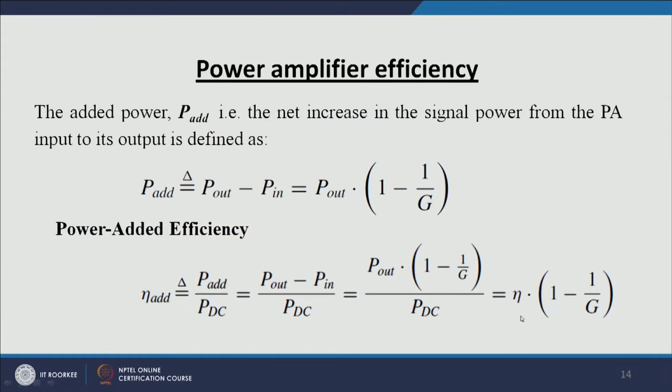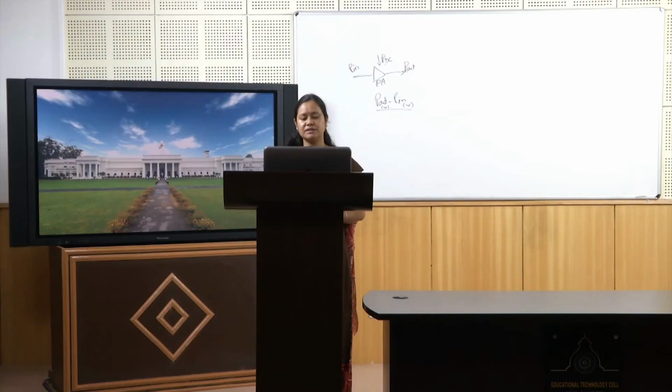So, if we know the drain efficiency and we know the gain of the power amplifier only, then also we can calculate the power added efficiency. So, in all these different forms we are able to calculate the power added efficiency.